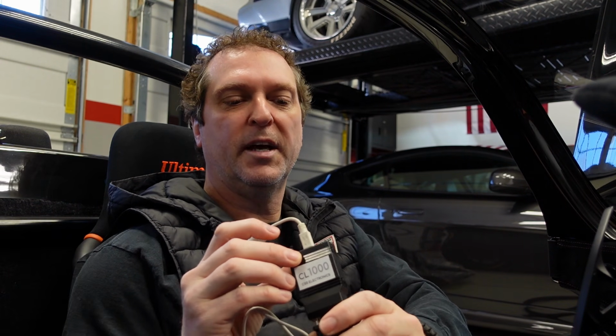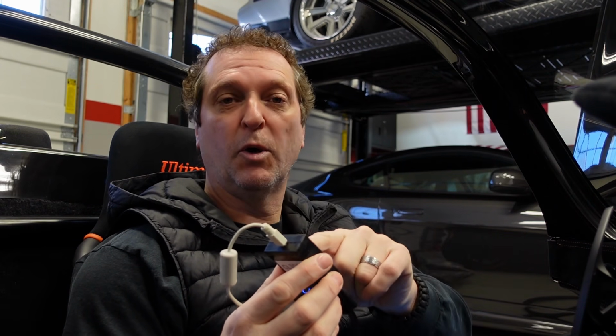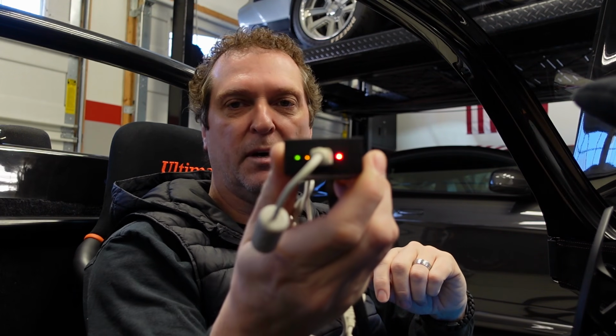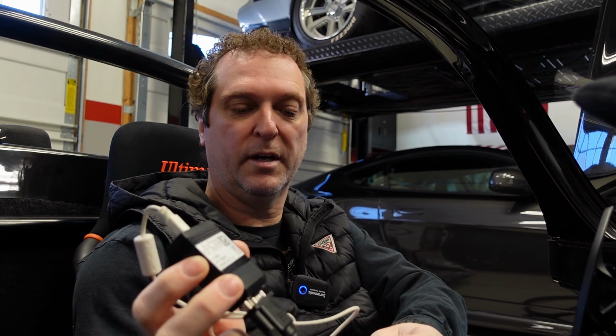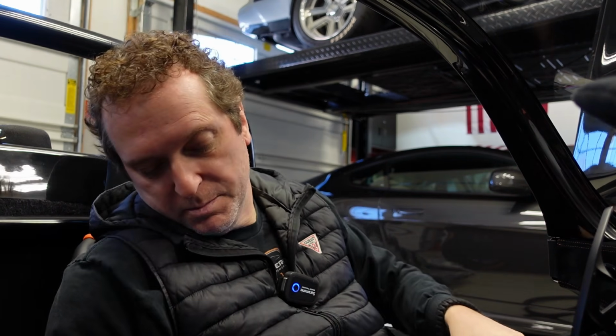Now, on my CL1000, as soon as it recognizes a CAN bus, it's going to start recording. So this is a headless device, which is nice. You can just plug it in, it'll just start recording. So you can see here, there's some blinking LEDs. That's what you want to see. That's when you know it's recording in real time. Now I'm going to plug this into my laptop so that I can stream that data directly to my laptop.